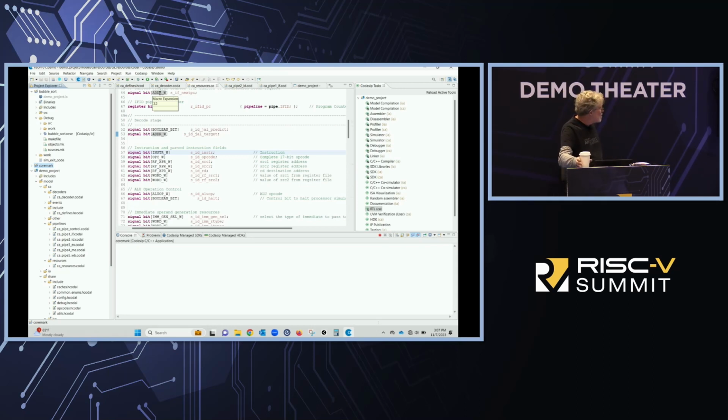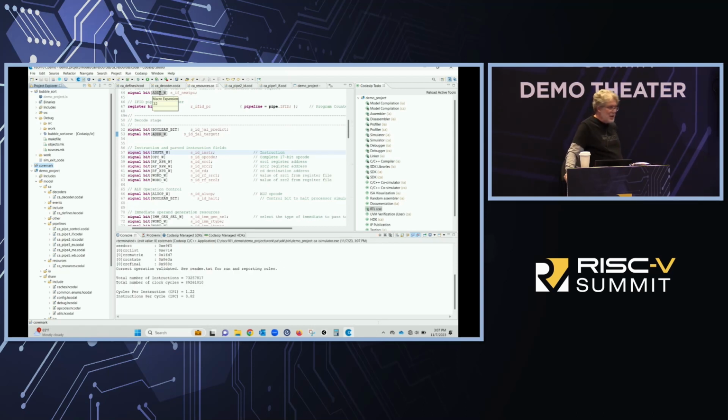Now, it should be almost ready. And after adding the compute resource in a minute, it will go faster. But you can see here that my CPI is 1.22, and the total number of instructions was 73 million, right? So I know enough about CoreMark that it likes to do multiplies, and the basic model from David Patterson, John Hennessy's book doesn't have a multiply. It's just an ALU, an add, and so forth.